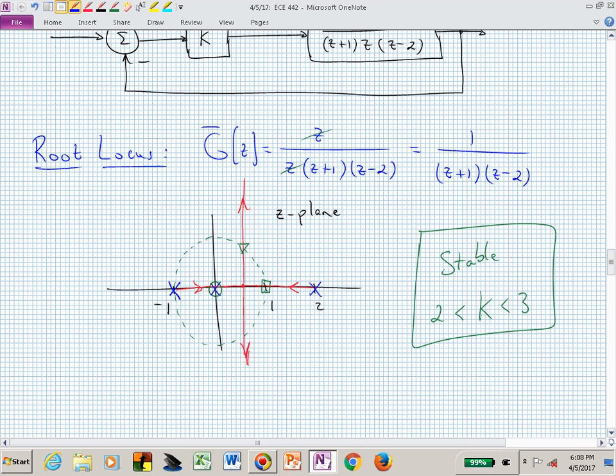So the question was, what would the root locus look like if you had a pole and zero canceling each other outside the unit circle? That should never, never, never happen. But basically, you would unfortunately not see anything. They would cancel, and so you would be misled into thinking everything was okay. And that's the fallacy or the myth behind canceling things outside the unit circle. You think, oh, everything is fine now, but it's not. You could have unbounded signals somewhere in your system that you aren't aware of during your design.